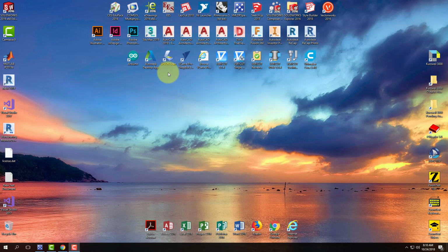And so you have to be careful. I found out on Monday that the AutoCAD in the laser cutter room has not been updated. So if you're working on AutoCAD and you go over to do some laser cutting, you have to make sure you save back into the 2013 version, which was the version before the 2018 when the major shift happened.